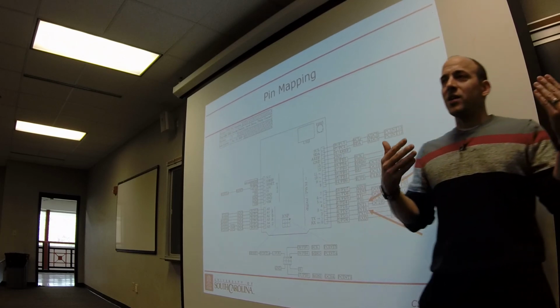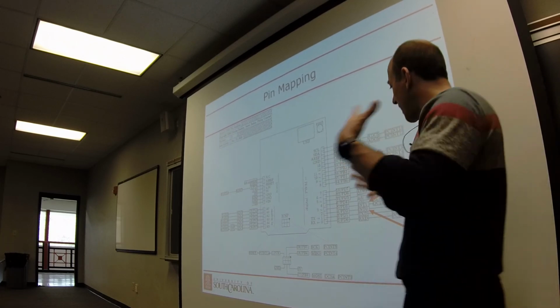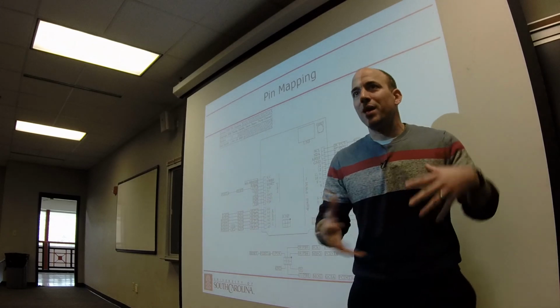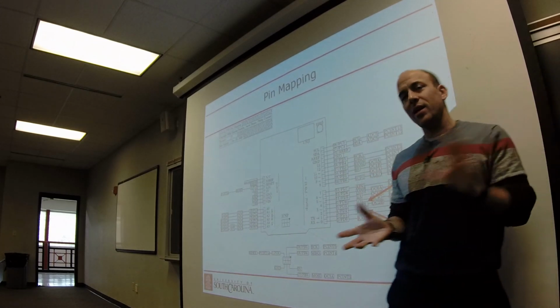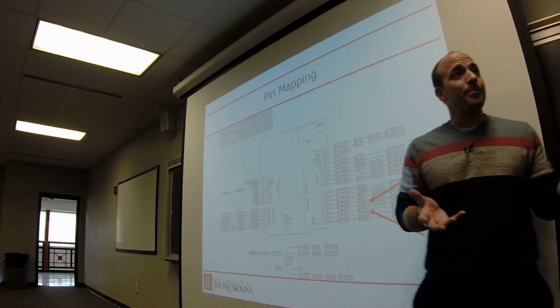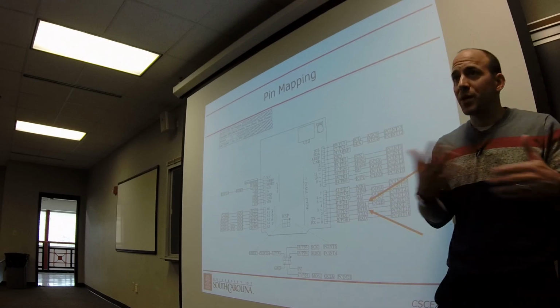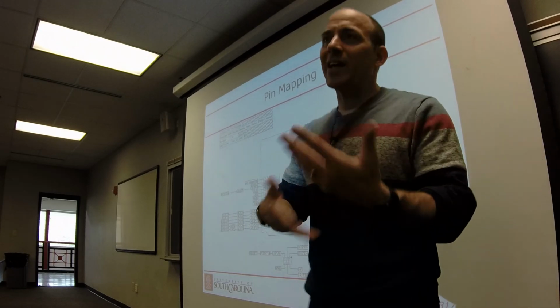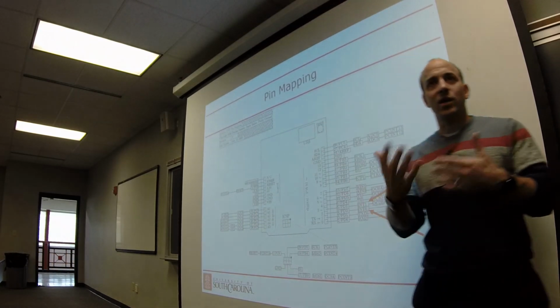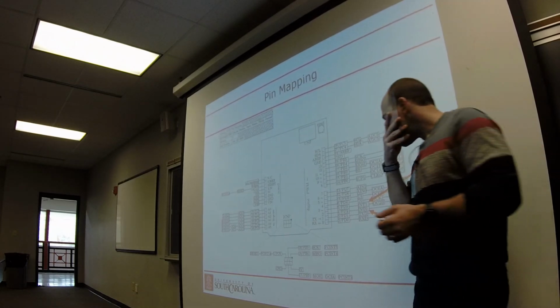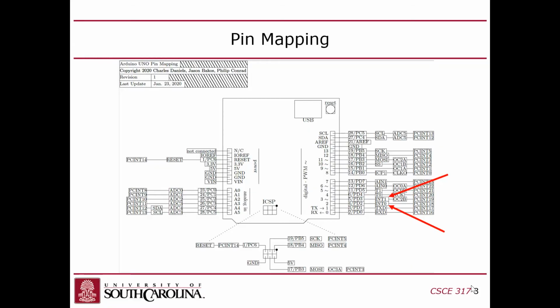But that's a nice way of doing it because then the processor could be doing other things in the meantime. It doesn't have to keep polling, in other words, keep asking over and over again in a loop if there's new data. So there are 2 external interrupt pins that are called int0 and int1. I've put arrows to them. They overlap with PD2 and PD3.